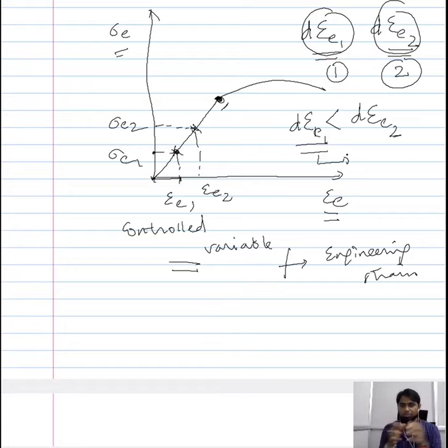So whatever values we get that show the deviation from the elastic point, or the deviation from the linear relationship between the stress and the strain, whatever point we want to calculate, it depends on the sensitivity of the testing machine. Such dependence is not usually accepted for our discussion. That is the reason why we changed the load to stress and deformation to strain. We don't want any external influence on either the behavior of the material or the response of the material, let alone the property of the material.